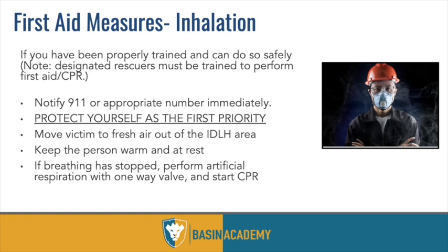Once you get them to fresh air through your rescue techniques, you want to make sure you keep them warm and at rest. And if the person has stopped breathing, you want to give them CPR. Avoid mouth-to-mouth in these situations because H2S may be in the air that's in their lungs and you may be exposed that way as well.